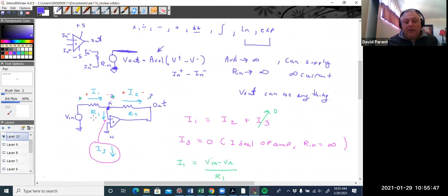So we have a circuit here. This current is 0 because the resistance is infinite. I have this feedback out put back onto X, right, through that resistor. And in is put onto X. But when you take the whole thing together, and this open loop gain is very high, Vx gets so small that there's no practical difference between the two.